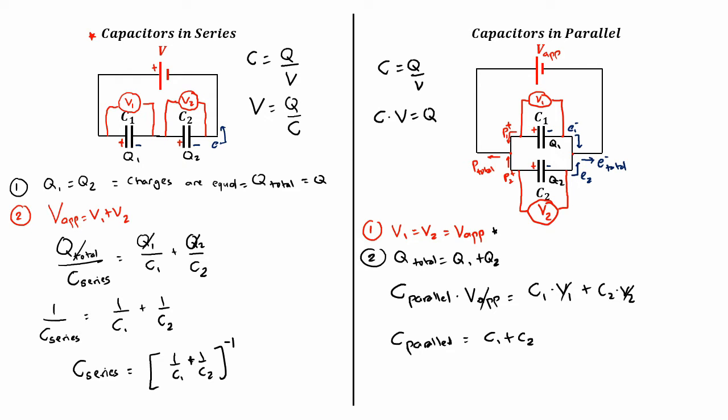But here, voltage equals Q divided by C, so we do not have a Q times C relationship for the voltage. Because it's a ratio, we end up with the two equations flipped in the capacitor combinations. Okay. Now in the next slide, we're going to look at what an RC series circuit is.